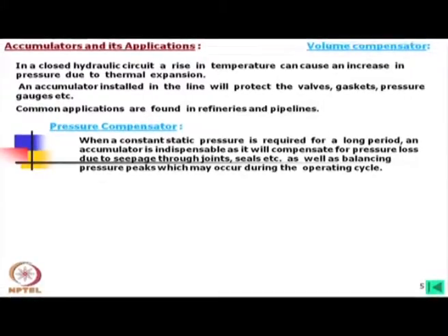we have to first keep in mind that when the pump is running, excess oil is being accumulated in the accumulator. Now, if there is a loss, suppose the system is stalled, that means a weight is lifted and then it is stalled, then there will be leakage, etc. That leakage can be filled by the oil from such an accumulator.